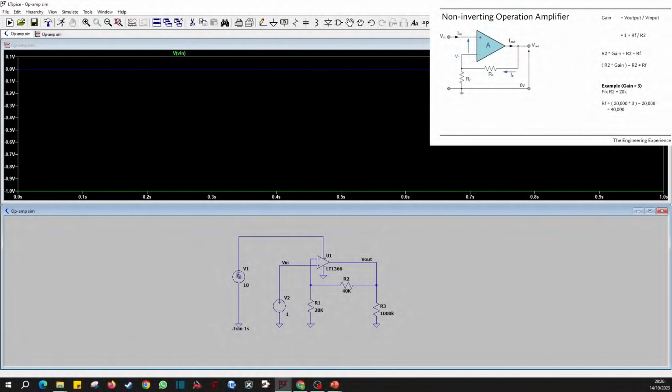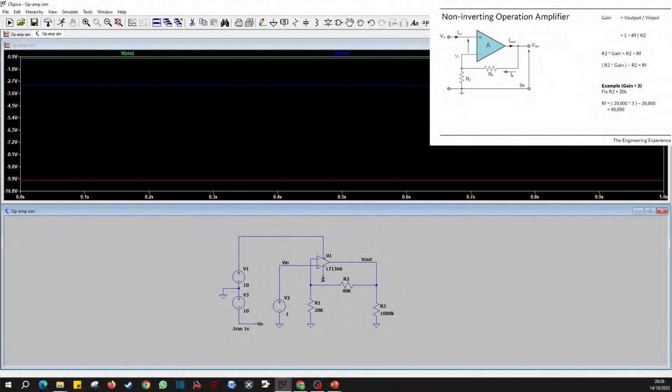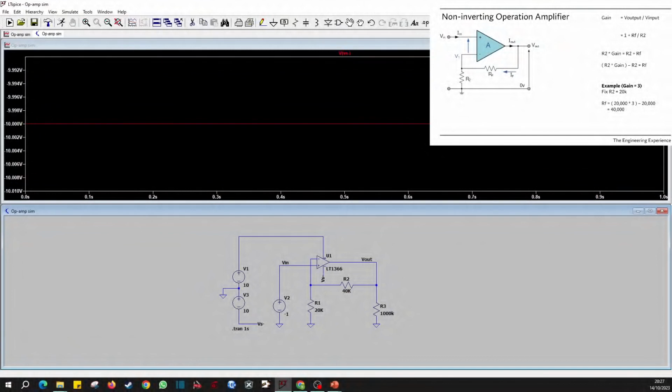We can fix this by adding a negative power source to the circuit, which should hopefully fix the issue that we are seeing. And I'm going to do this with net labels. So you can see, go to net Vs minus, and I'm going to connect that here. And then I'm going to move the ground to the middle of this. So this means we now have a -10 volt supply, and I'll show you that in the circuit, in the simulation model. So you can see we've got a -10 volt supply going to the op amp.